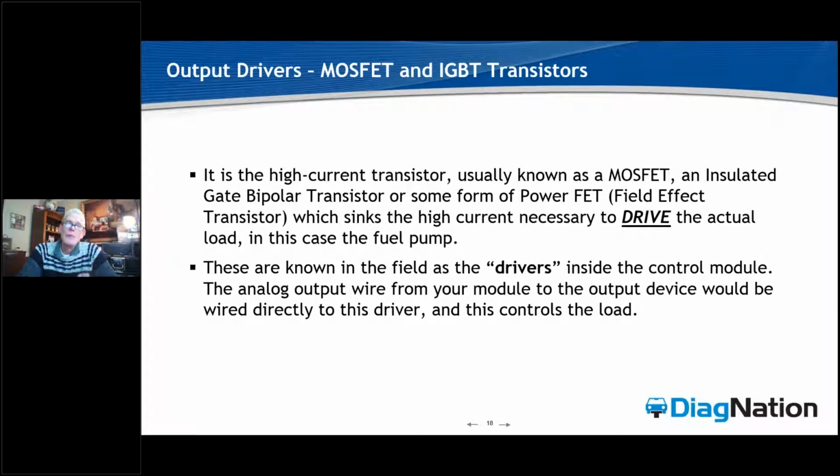It cracks me up when you see these guys driving around with a check engine light on and a P0303 misfire for 4 weeks waiting to get the car into the shop. Most of the time, guys, by the time you've waited 4 weeks with that kind of reflection, secondary ignition reflection traveling back on that primary circuit, it's just frying the transistor and it's working on that PCM every single time that rogue coil fires.